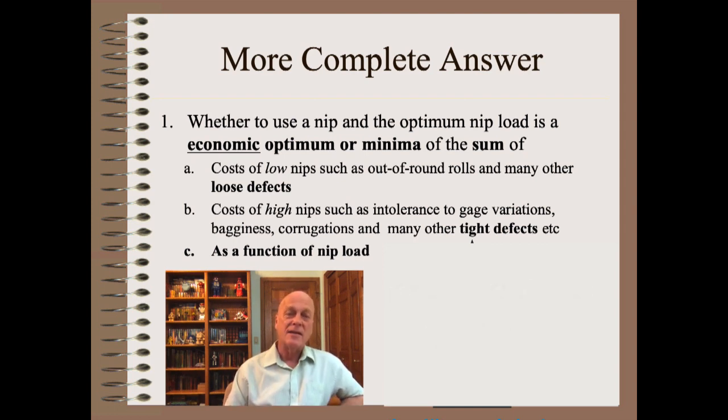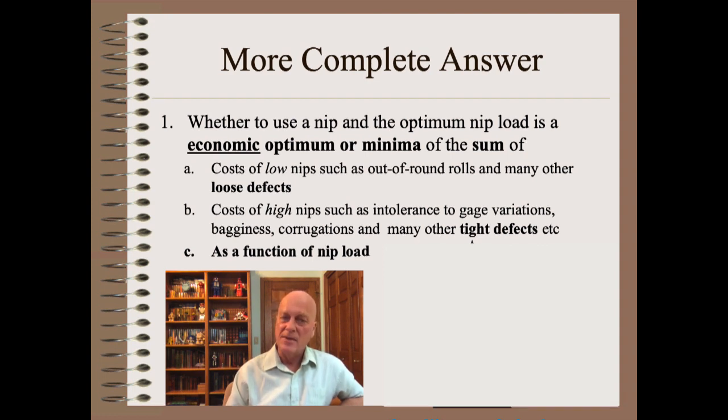The executive summary goes something like this. Nip is the most powerful of the winding tightness knobs. It is also, at the same time, the most destructive of the knobs. It will require a nearly dead flat web thickness profile to use nip of almost any value.